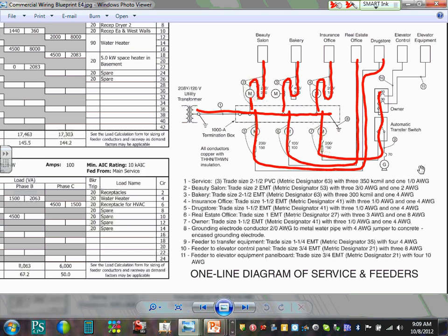So I have a building that has how many tenants? 1, 2, 3, 4, 5 tenants in this building. 5 tenants, and each one of them is having a power of his or her own, and I have a gutter here. Can you guys see the way they did it? They brought the service into a gutter, a box, and they fed from this gutter a disconnect fuse. A fuse disconnect like this with a meter right underneath it. The cheapest way of feeding a commercial building, you're going to see this one there for strip malls. Very common for strip malls.